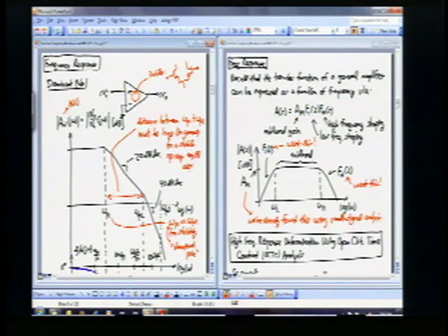It's a more complete Bode plot than this one. The Bode plot to the left is basically showing everything from this point on, but it's not showing what really happens when you get really close to zero frequency, to very low frequencies. Remember, there's no zero frequency on this because that's log omega. This just keeps going to 0.00001, but it never goes to 0 because it's log omega.